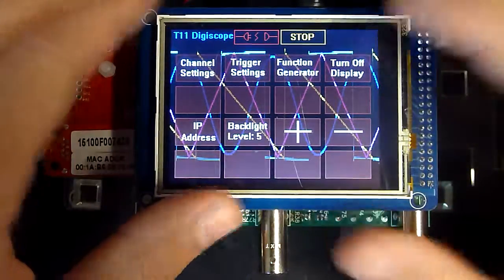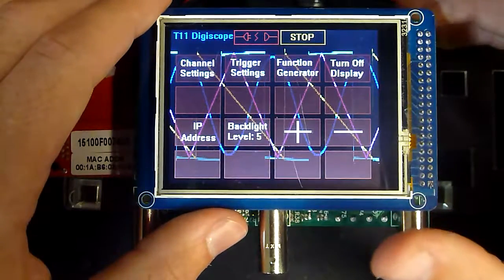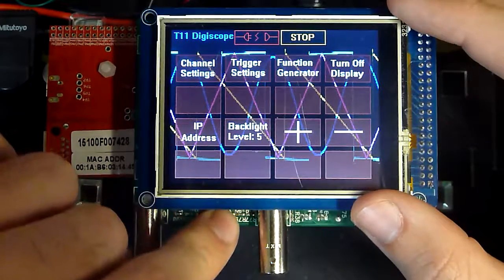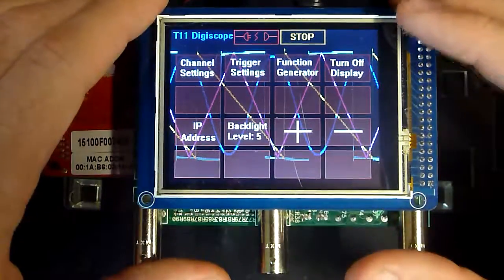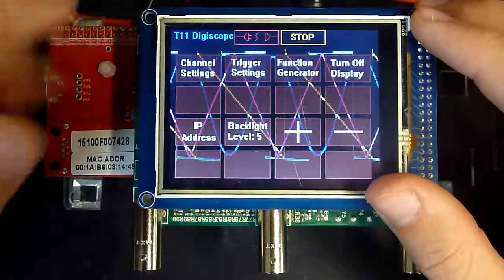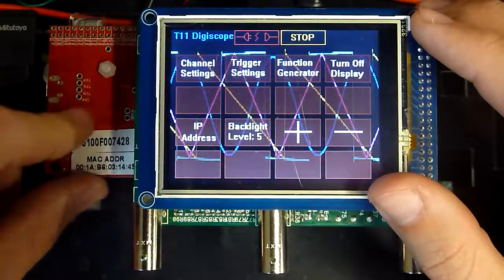And so this was a big project. We all had parts to do, and my part was the LCD touchscreen interface and the analog front end on the PCB below that did all the signal handling and then presented the signal appropriately conditioned to the ADCs to then be processed and then sent over Ethernet to the PC software to be displayed.